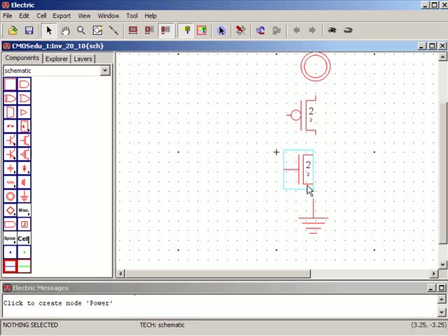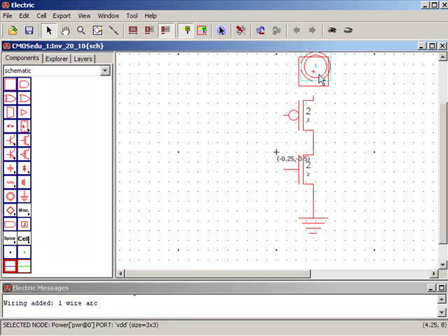If I want to connect a wire to this port, I left click, and now here's something you've got to get used to. Then I go close to the port and I right click and drag, and I connect the port like that. So here I'm going to move this one over a little. Then I'm going to right click and pull down. So selecting with the left mouse button and then connecting the arcs between the node ports with the right mouse button is how we do this.